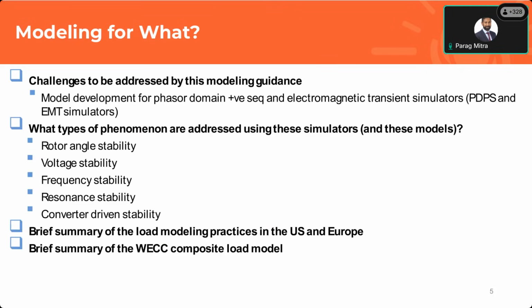Won't go through all of them, but what I want to do is highlight some of the key things that we cover here. So the first question is modeling for what? Modeling is a very wide or a very overarching term. You could be modeling for a lot of things, but this particular document specifically talks about modeling for positive sequence phasor domain simulators, and electromagnetic transient simulators.